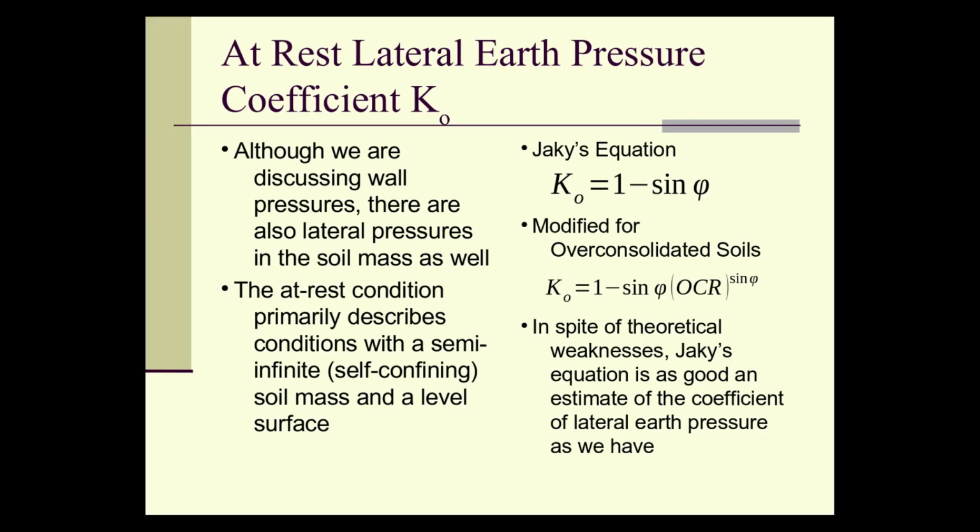The at-rest lateral earth pressure coefficient, K0, also exists in the soil mass. In fact, it principally exists in the soil mass. The at-rest condition primarily describes conditions with a semi-infinite soil mass and level surface. It can also describe a wall which is quote-unquote unyielding. And some of you have probably figured out that there is really no such thing, that walls are going to move some, it doesn't matter how much.